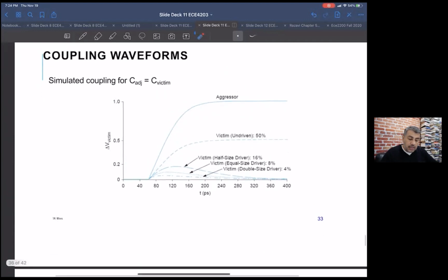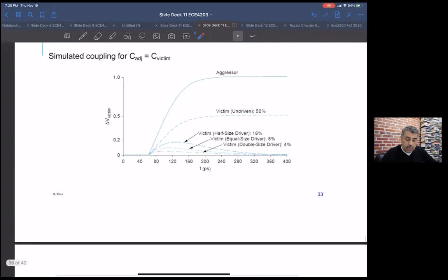So again, at least it doesn't flip the line, in terms of this crosstalk. But because your victim has to charge this point back down, the NMOSFET here is working to keep this capacitance from going up and bringing it back down. You're actually creating a current condition to discharge this capacitance back down, which is adding to the power consumption.